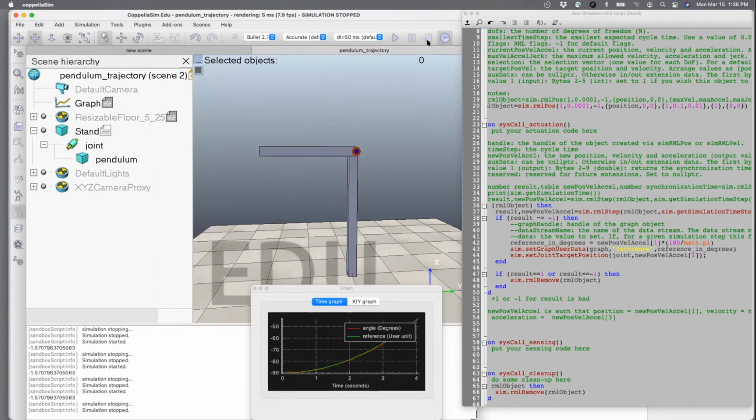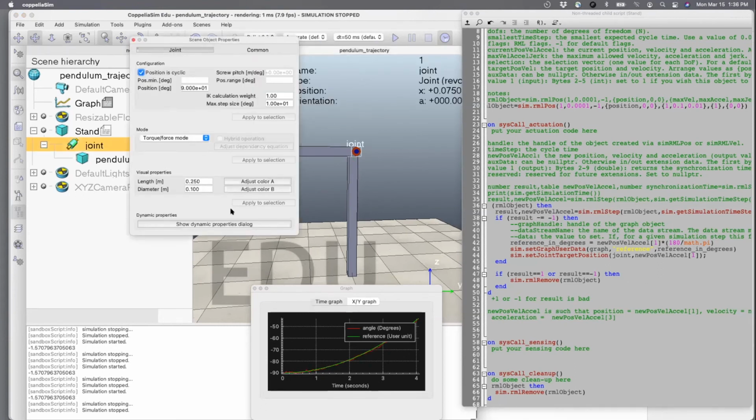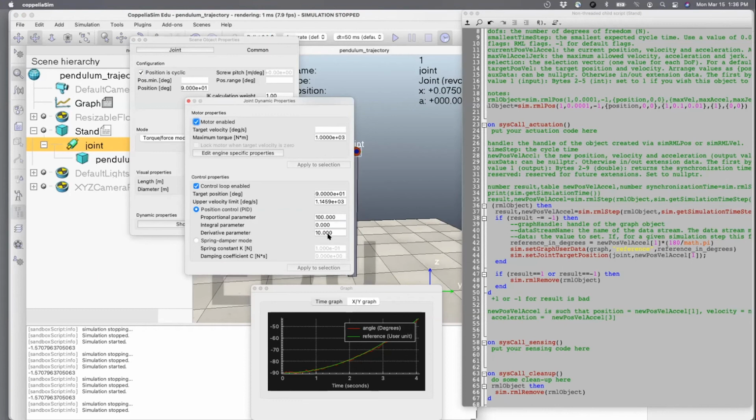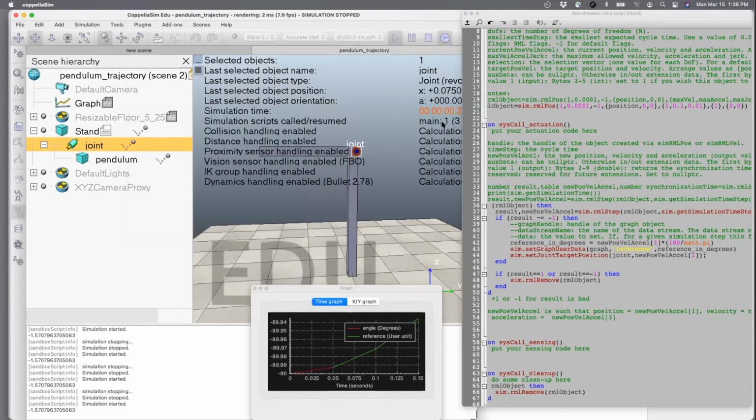The way this can be fixed is by tuning the PID controller. If you go to PID here, I set it to 110 for the D. You really don't need such a high value. Just put 1 and 0.1. This is just a proportional controller, and then see what happens. Okay, clearly it's doing very good tracking.